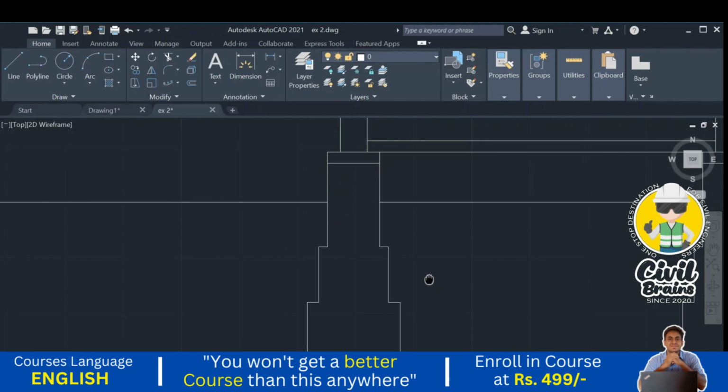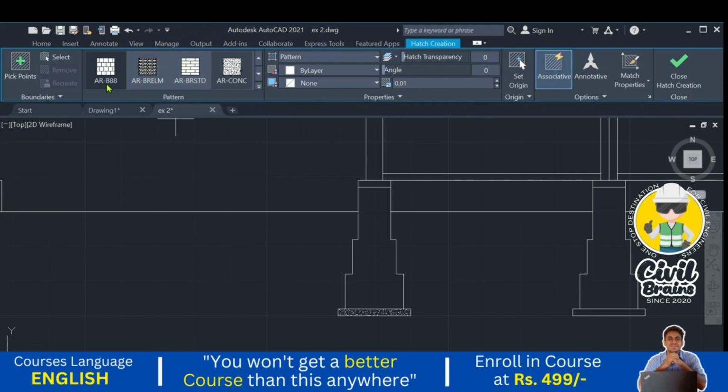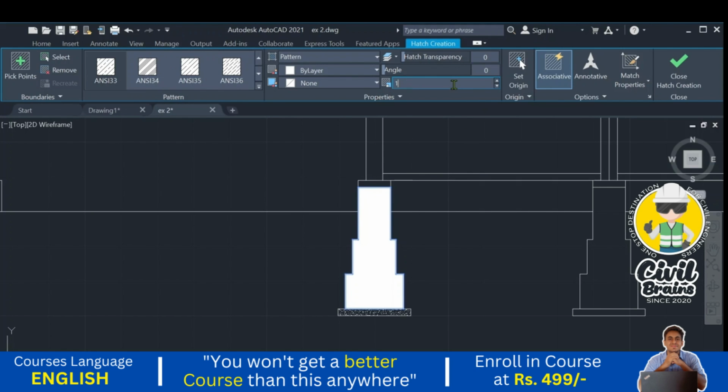Next we need to hatch the foundation. Go to the hatch command, foundation PCC. I said that ANSI 32 is for superstructure or burnt brick masonry, and for the foundation we need to show ANSI 33. So one straight line and one dotted line is for foundation, and two straight lines for superstructure. I click here. Scale, I change to 0.5. 0.5 is okay.